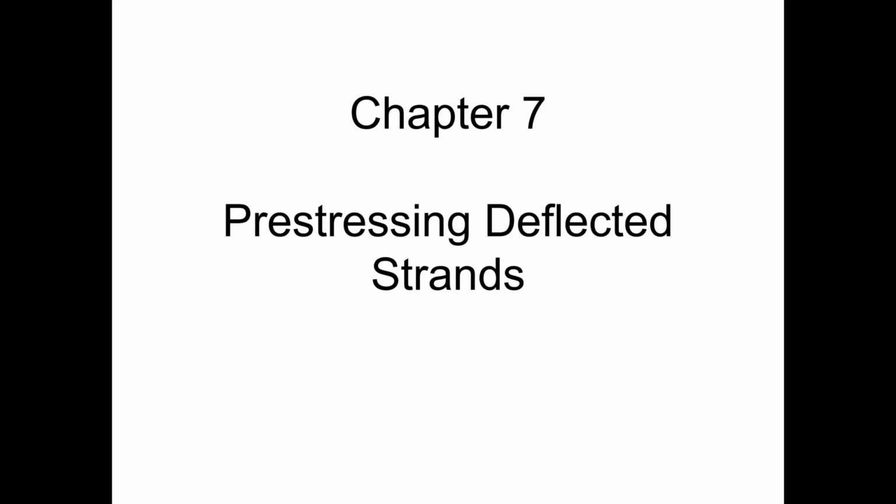So in Chapter 7, we're going to be talking about pre-stressing deflected strands. Now there's some terms that we'll be using interchangeably, and you will hear them used at plants interchangeably. Draped, harped, and deflected all refer to the same condition. So there isn't any technical difference between those three words. I may use all three of those terms as we go through our discussion today, and you're likely to hear all three of those terms used out in the industry as well.